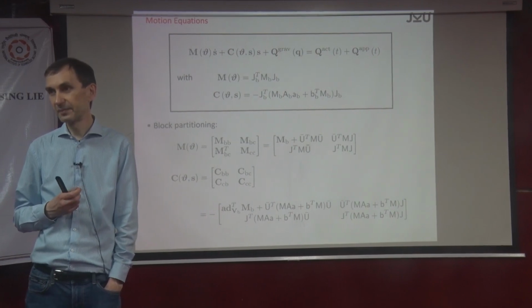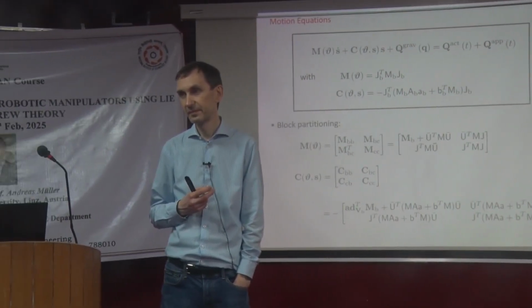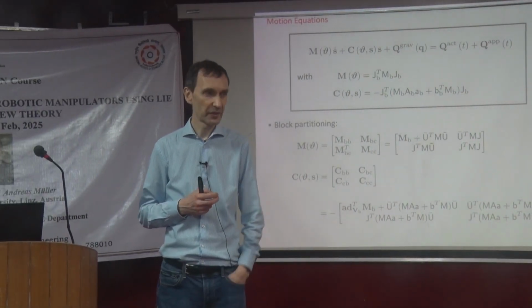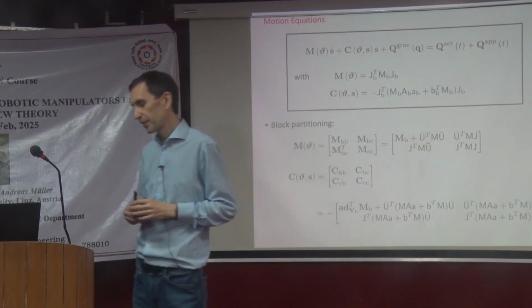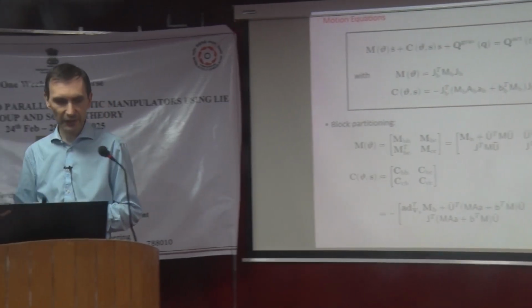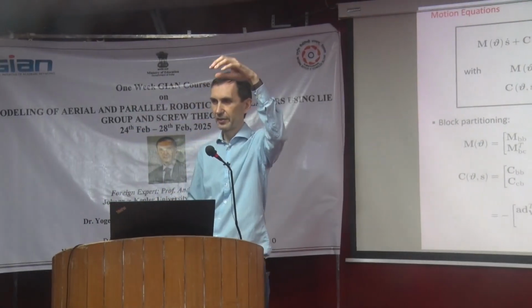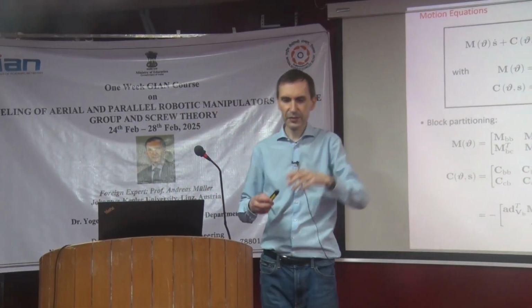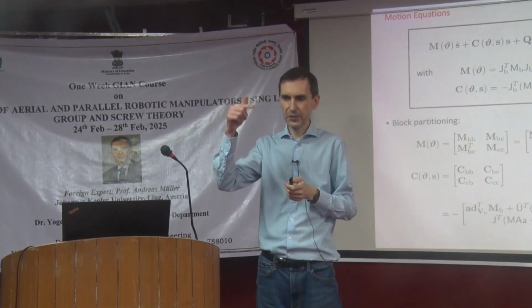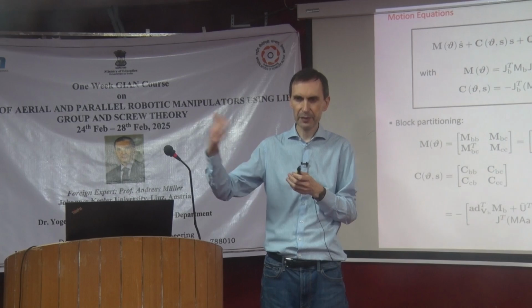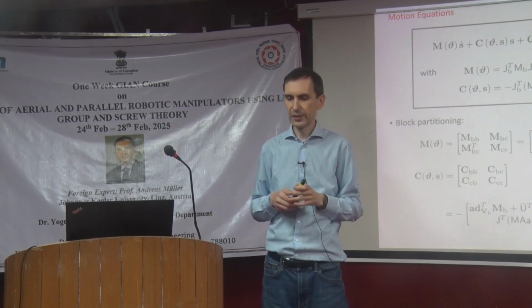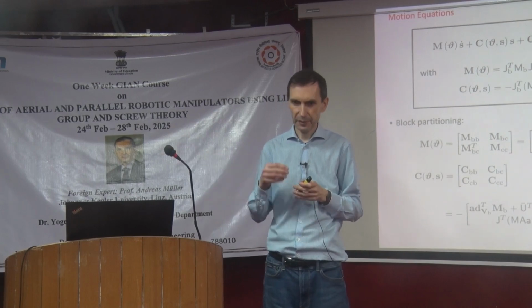The spring mass system is a linear kind of system. Yeah, that was not a good idea to say linear. So what you do, you have this robot, right? So a certain robotic chain, kinematic chain. Then for each of the joints, you give it an excitation with a certain frequency, and then you change the frequency, right? So you have like a sweep.